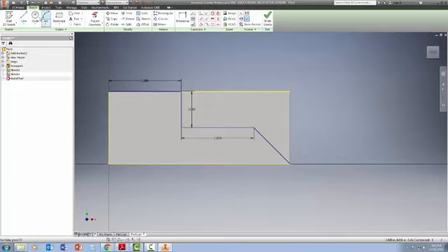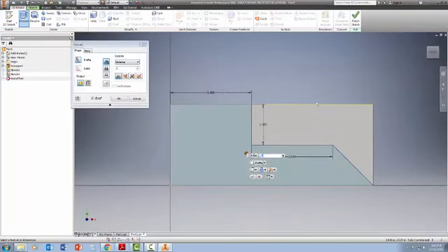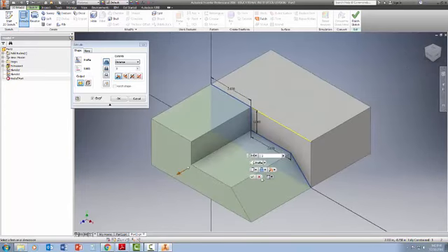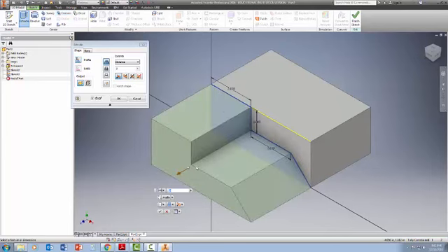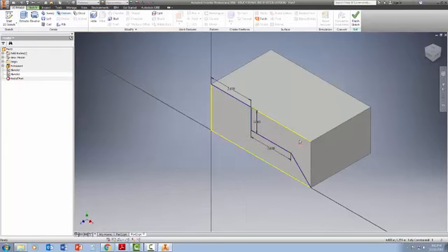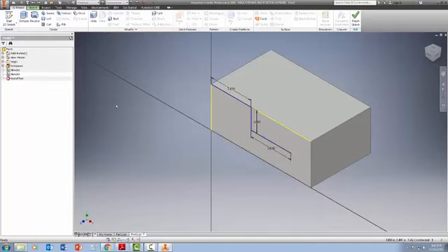Next thing I have to do is extrude, and I want to extrude the area that I'm trying to get rid of. So it thinks I'm trying to get rid of that, but I'm not. So let's do this area. Okay, so let's say, oh no, what's going on here? Why isn't it letting me do this? Okay, a common problem is that you'll have 2 different sketches and you're trying to do 2 different things. It doesn't know that they're working together. It just thinks that they're completely separate.